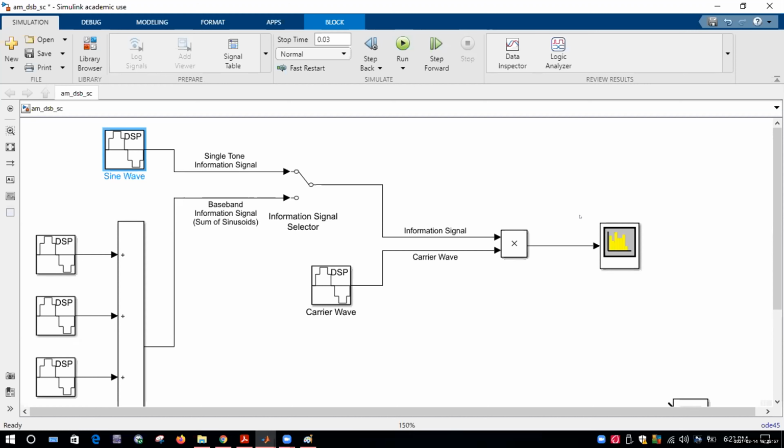How much, Mr. Samir? 2 plus 15, 17. And 13. Remember, this type of modulation where you're multiplying carrier and information is double sideband modulation. So in the output, you should only be able to see two signals, lower sideband and upper sideband.